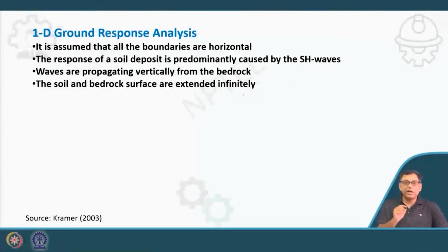Okay. Now, what are the assumptions in 1D ground response analysis? Here we are considering only the vertical direction, the motion of the wave in the vertical direction. That is why it is 1D ground response analysis. It is assumed that all the boundaries are horizontal.